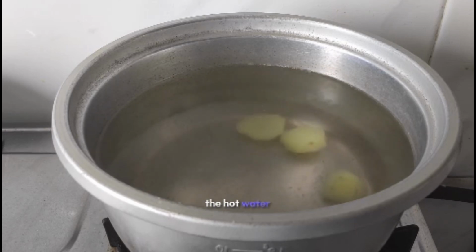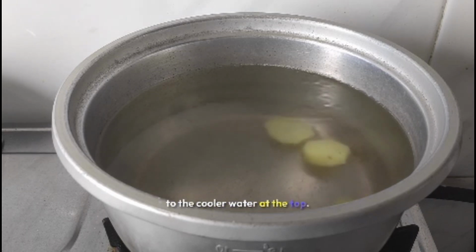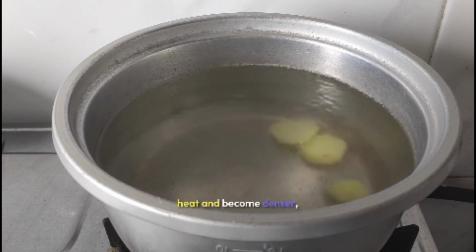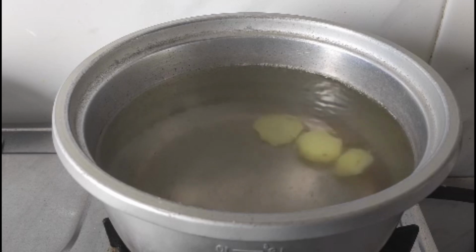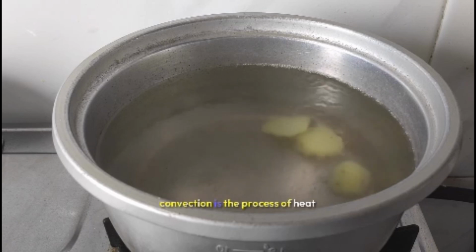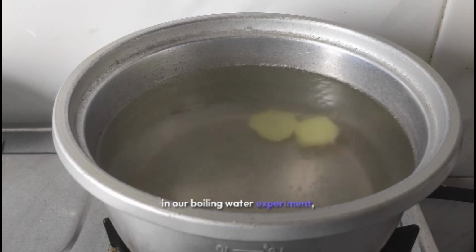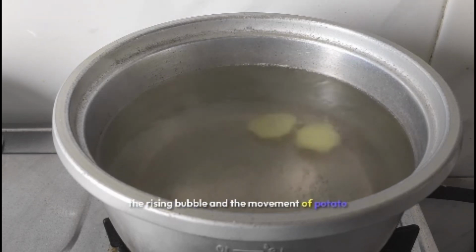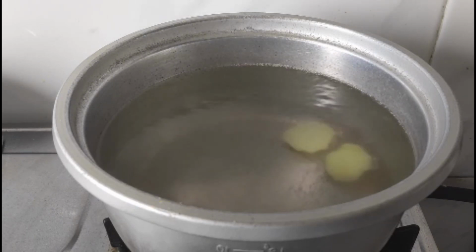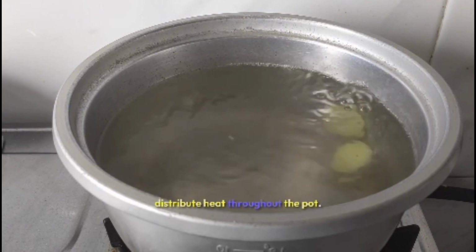In this experiment, the hot water and bubbles rise from the bottom, transferring heat to the cooler water at the top. As the hot water reaches the surface, it loses heat and becomes denser, causing it to sink back down. This cycle repeats, creating a convection current. So, in summary, convection is the process of heat transfer through the movement of fluid. In our boiling water experiment, the rising bubbles and the movement of potato slices clearly demonstrate how convection currents work. Hot water rises, cools at the surface, and sinks again, creating a continuous flow that distributes heat throughout the pot.